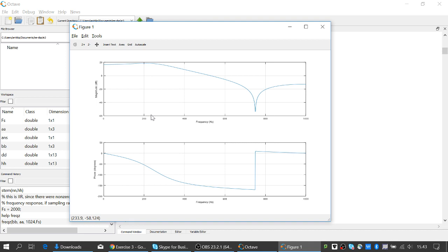A really fast filter, almost the same as a 4-point running average filter. And we have some gain on the passband, about 18 dB, but on the other hand, this is minus 18 dB. So we have the stop band attenuation something like 35 dB compared to that 10 dB of running average.